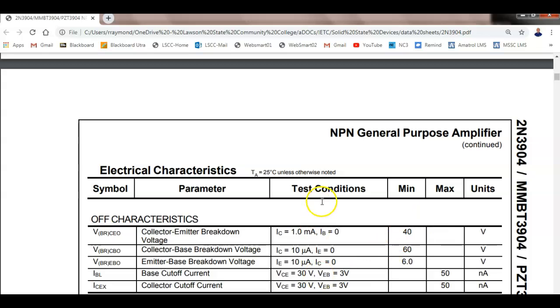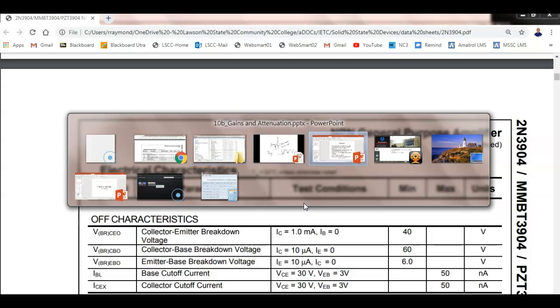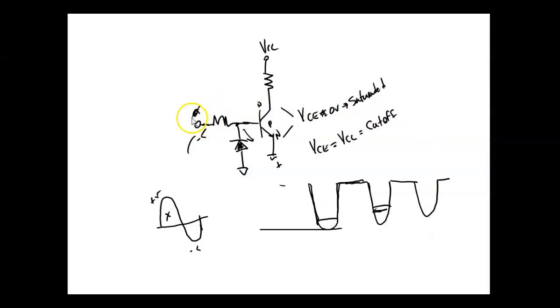So what the diode does, it prevents that from ever happening, right? You'll see this a lot on saturated switches, especially working with AC. If this goes negative 5, that forward biases this diode, so I'm only putting a negative 7/10 of a volt on my base. So this protects the diode. When it goes positive, this is reverse bias, and it puts a positive on the base and turns the transistor on. But it still wouldn't do AC. It would still clip off the negative alternation, right?